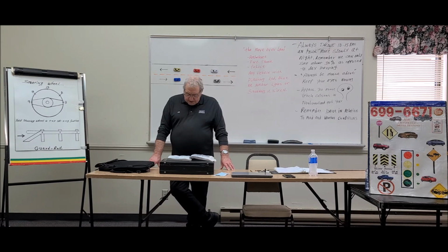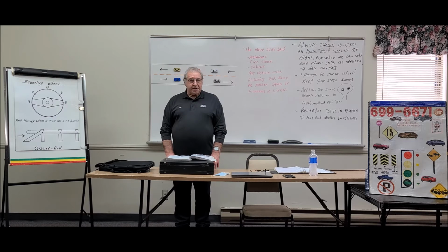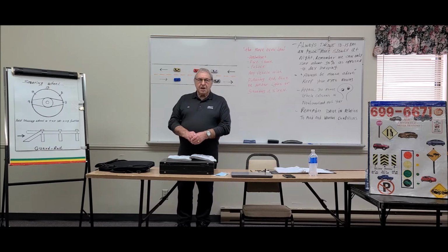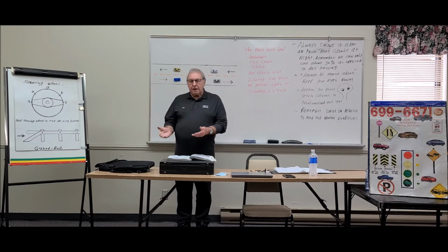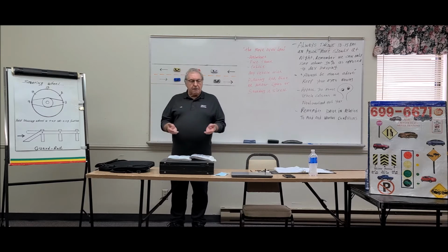And they tell us there to avoid turning the steering wheel when the vehicle is stationary or not in motion, in other words, what they call dry steering. And that's the thing about it, particularly when we're angle parallel parking, we're doing a lot of turning of the steering wheel. And of course, if the vehicle is stopped, then we're scuffing the tires from right to left or left to right, and that causes rapid wear to the underpart of the tire in that particular area.